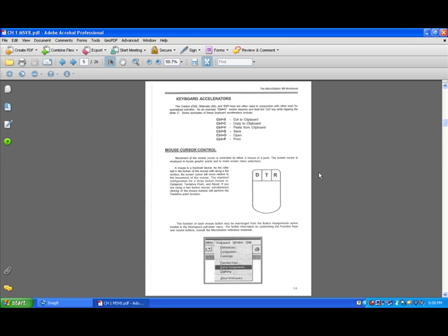The right is a reset, meaning when you're done using that particular tool, you hit the right mouse button and it stops and you let go to grab another tool. So if you're drawing line strings, you're continuing to put points on the screen until you hit that right mouse button to stop it. So you can do multiple points for the line string. Again, down here it shows you how to adjust those button assignments.